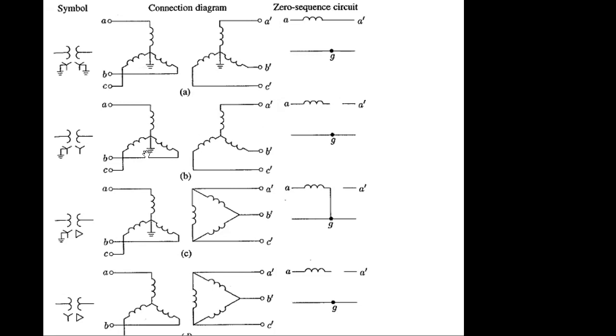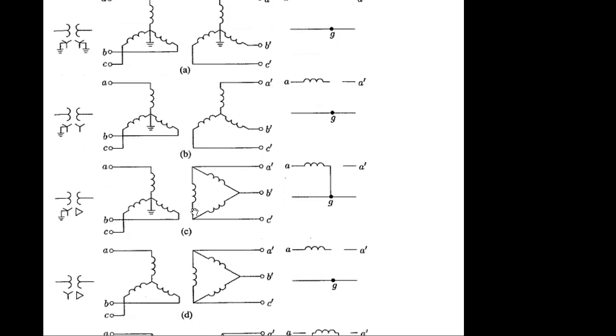Why? No. Here you can see the transformer symbol. Which part has ground, primary or secondary? Secondary. Secondary has open, right? So secondary open, that means this path is the secondary side, which should be open. Okay. And if it is Y delta, in that case, the configuration will be something like this. That means the zero sequence transformer equivalent circuit for Y delta, you will have the configuration like this.